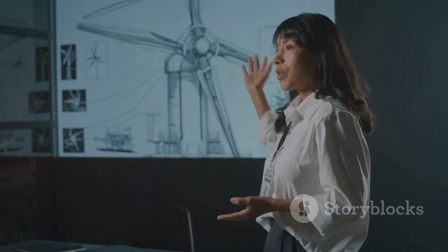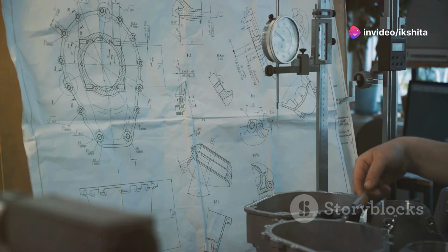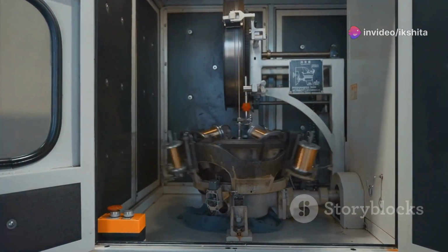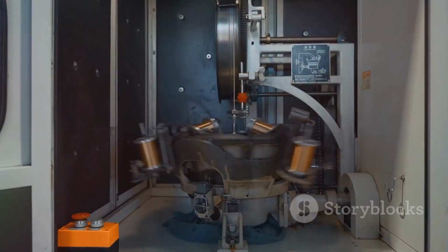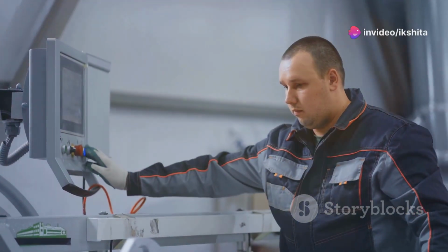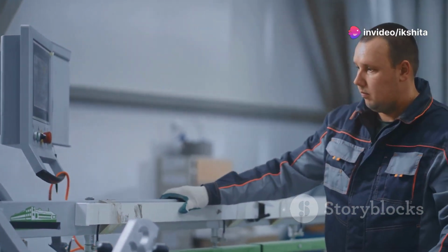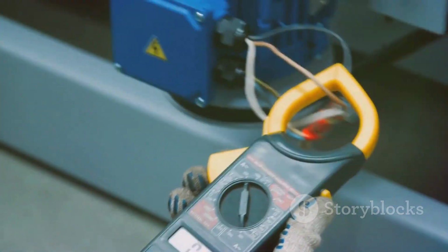Section 8. Wrapping it up. Key takeaways. So, there you have it, armature reaction in a nutshell. It's the magnetic interaction between the rotor and armature fields in synchronous machines, influencing their performance. Remember these key takeaways. Armature reaction can strengthen or weaken the main magnetic field, depending on the power factor. Lagging power factor boosts the field, while leading power factor weakens it.